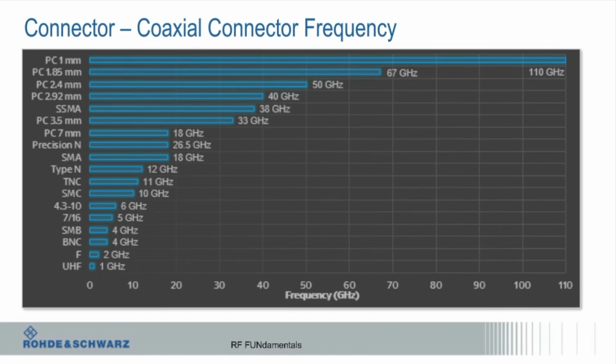The reason we beat these to death in terms of connector types is because people always use the wrong ones. They'll say, I have an SMA cable. I had a guy at a digital company with an SMA cable, and he was trying to measure something at 110 gigahertz. And guess what? It didn't work for squat.